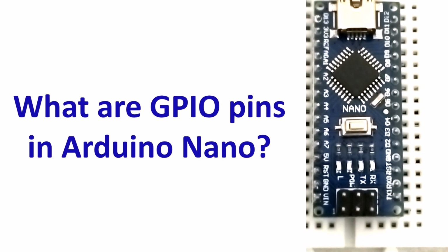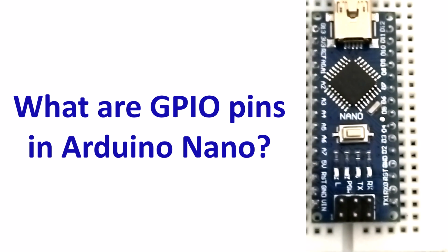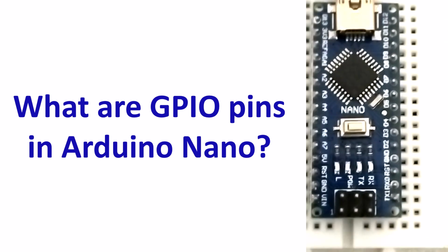GPIO pins in microcontrollers like Arduino Nano are general purpose input-output pins. They can be configured by software to act as either an input or an output. This allows them to be used for functions like reading sensor data as input pins and controlling LEDs or motors as output pins, or interacting with other devices.